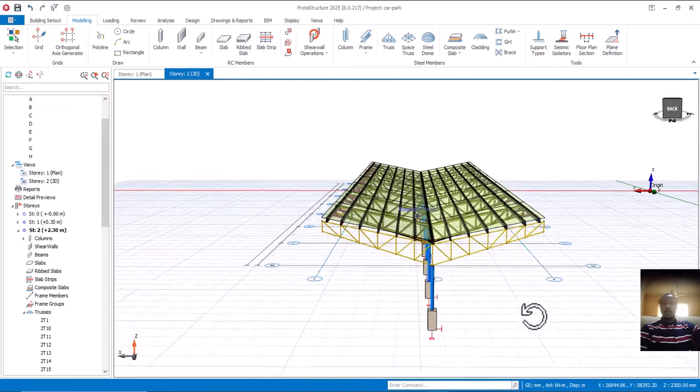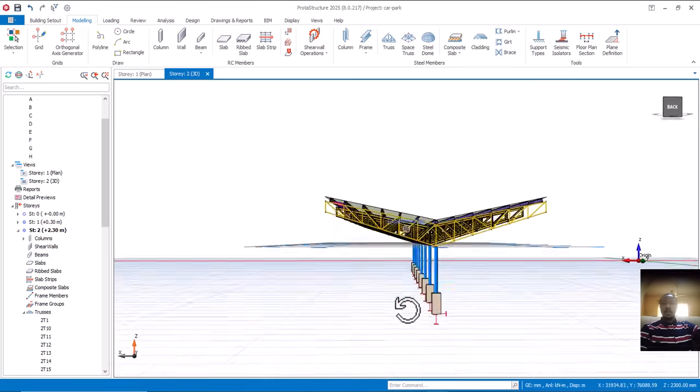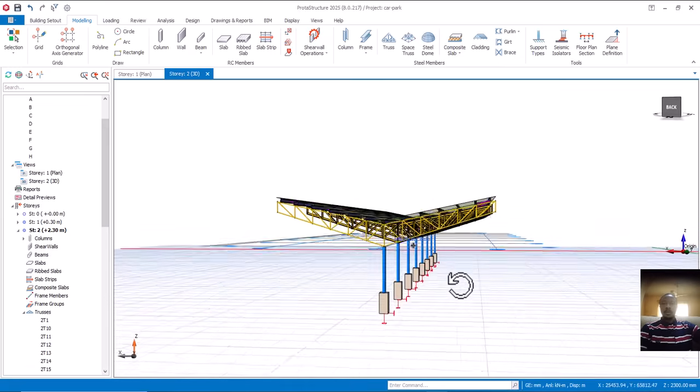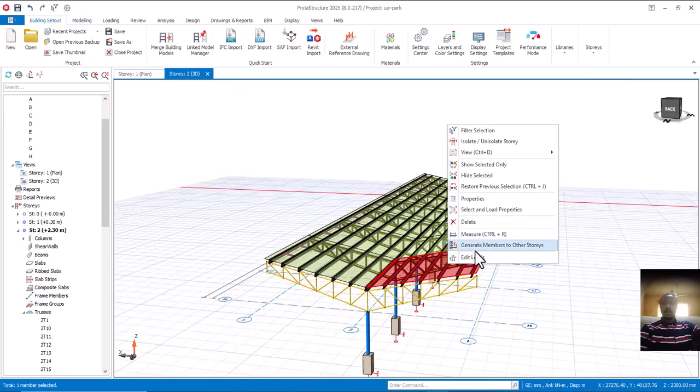So how do you now apply the wind load to face this direction? We can apply the load so it faces from the top like this. Wind is affecting from the top, also from the top here. But how do you now apply the wind load to under like this? How do you apply the load under it? So let's now go into that. All right, so click on this, right click and click on edit load.